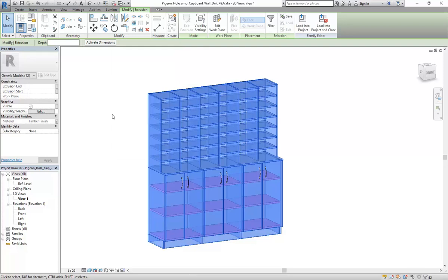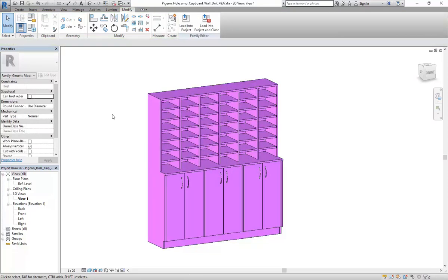Yeah, no, you just got to assign a parameter. That's it. It's that easy. Assign a parameter. You can do this to any family in Revit. So most of the things you'll download on Revit City won't have a parameter set up. But again, all you have to do is assign your own. And like I've been saying, Revit's a management tool. It's always got the options to manage things however you like, but you have to set that up.